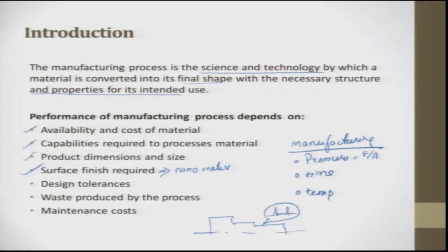Something like this. Here, when you mate it with a bolt, or with another contacting surface, the contacting surface will sit on these peaks. These peaks over a period of time get destroyed, and they fall in between the two mating surfaces. In the beginning, the load bearing area will be very less if you have a rough surface. That is why people talk about getting a nano finish surface. Nano finish means these peaks will be very few, so these peaks would now have changed into peaks something like this.